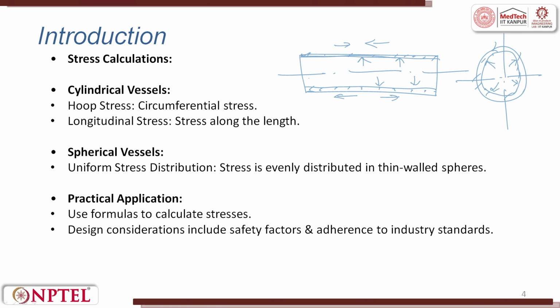Spherical vessels: you can see where they store petroleum products, a tank will always be spherical in nature. So, it will have uniform stress distribution. The stress is evenly distributed in the thin walls. Practical applications are where you can use formulas to calculate the stresses, and design considerations include factor of safety and adhering to the industrial standards.